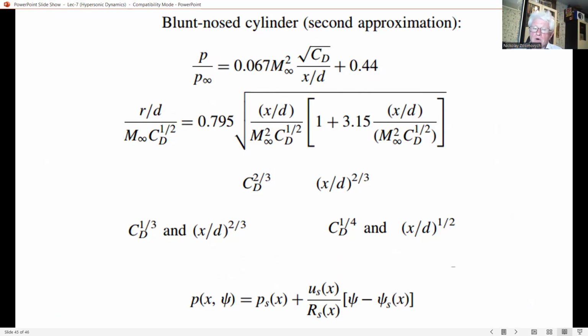Here we observe, both experimentally and from the governing Euler equations with the appropriate boundary conditions, that certain non-dimensional aerodynamic quantities such as Cl, Cd, and Cp become relatively independent of Mach number above a sufficiently high value of M infinity, which for blunt bodies can be low, around Mach number 5.